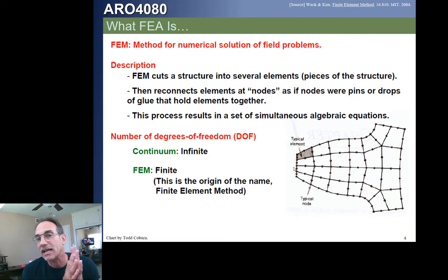So we're going to be using things like nodes. We're going to be identifying points in the model. We call these either nodes if you're using Abaqus or Strudel, or grids if you're using NASTRAN. We're going to develop elements like rod elements and bar elements. Rod elements have axial capability. Bar elements have shear and moment capability. Plate elements, you can deal with flat plate elements like a quad element, a CQUAD element in NASTRAN, which would have 4 corners and have in-plane stiffness and other higher elements. We're going to look at some of these.